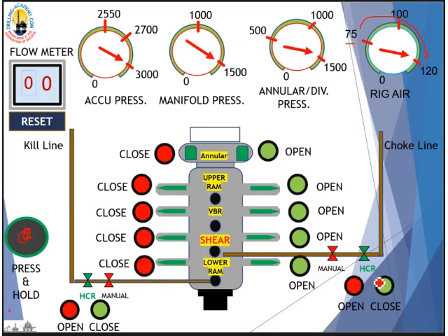But for the HCR valve, it's the contrary. When it's open, it's red. And when it's closed, it's green. All right? And don't forget about the manual gate valve in front of the HCR valve. All right? It is for isolation if you have to repair the HCR valve.